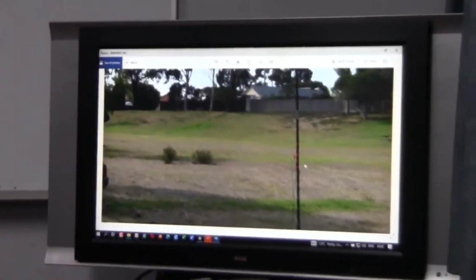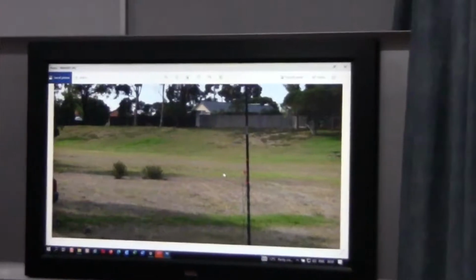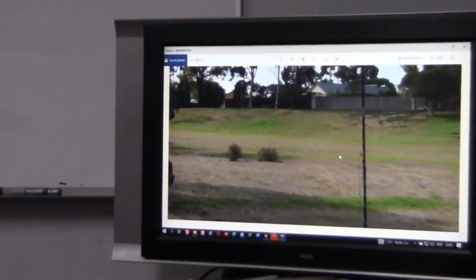Same thing. Anyway. So elevated ground radials, there's been some experimental work done that shows that only a few radials elevated above the ground can be as efficient as a reasonably extensive radial system of wires laid on or just slightly below the surface of the ground. So it has its merits, especially if you want to take a portable. All right, so with that in mind, let's proceed. Still not ideal. Okay.